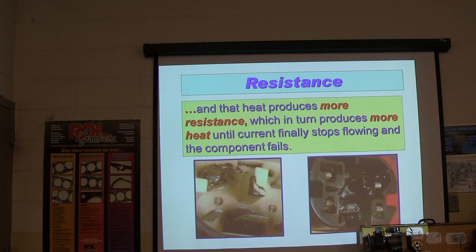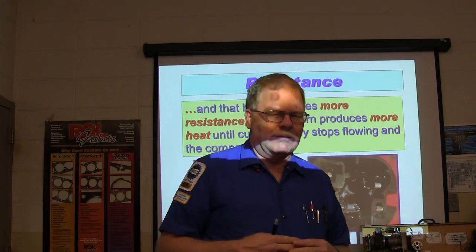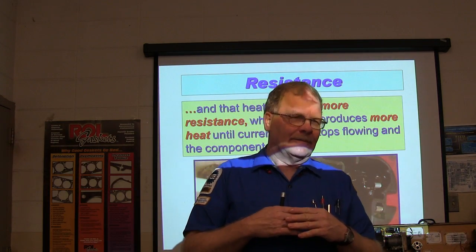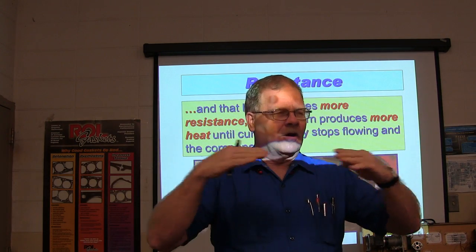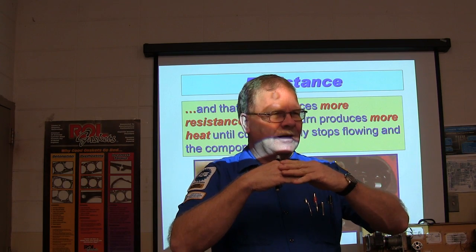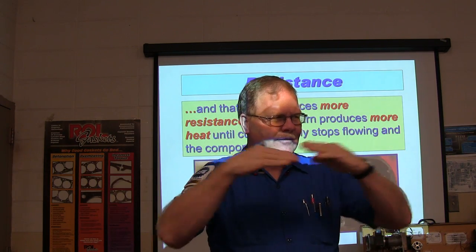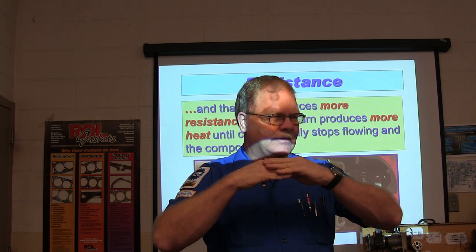There was a GM instructor one time, at a GM school my buddy Donnie went to, and that guy said that when you unplug connectors on a GM car and plug them back together 4 times, you're probably going to start having trouble with them. Because they're not really made to be unplugged and plugged back in very many times. The first time they're plugged in, they've got the best connection they're ever going to have. And sometimes it ain't that good.